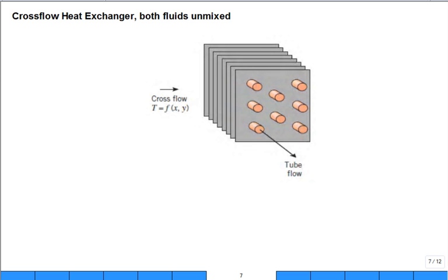We see a lot of cross-flow heat exchangers. You pop the hood, you look at your radiator in the front of the car. What type of heat exchanger? Is it shell-and-tube? No. Concentric tube? No. It's really cross-flow. So you have a manifold, either top or bottom, and the liquid water and ethylene glycol mixture flows left to right or right to left, sideways or up and down, depending on your radiator. And then the air flows the other direction, cross-flow.